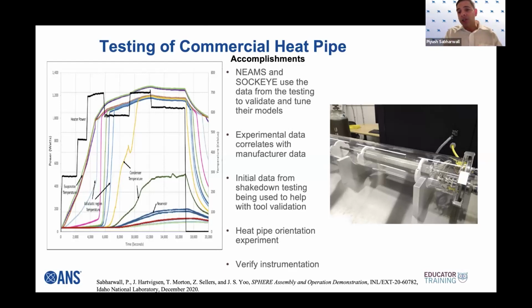We do this also at possibly a different orientation. So we can orient this at different angles to see the effect. And also look at instrumentation. What do I mean by that? Conventionally, we use thermocouples or pressure transducers for measuring pressure, thermocouples for temperature, right? But there are some fiber optic sensors that are being looked at. So we have both sorts of sensors in it.